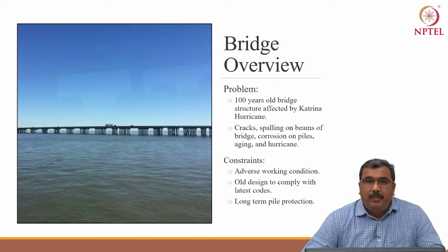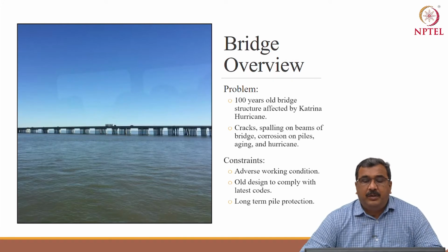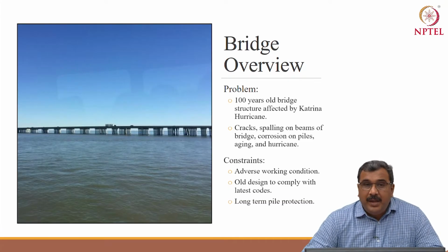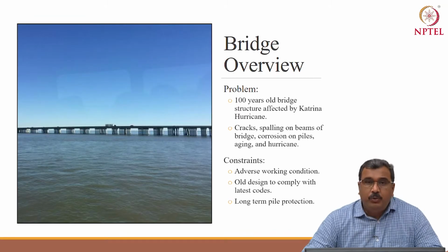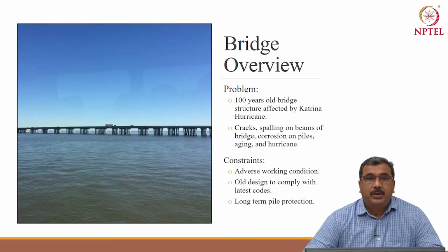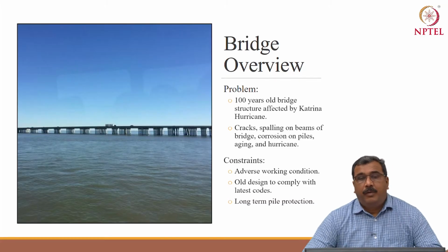You can always replace a partial deck of the bridge, span by span. This is a common practice in USA and Canada, that is North America. But to replace the pile, it's not that easy. So they wanted to carry out pile protection, like protecting the pile against corrosion and strengthening it for a further 50 years or more.